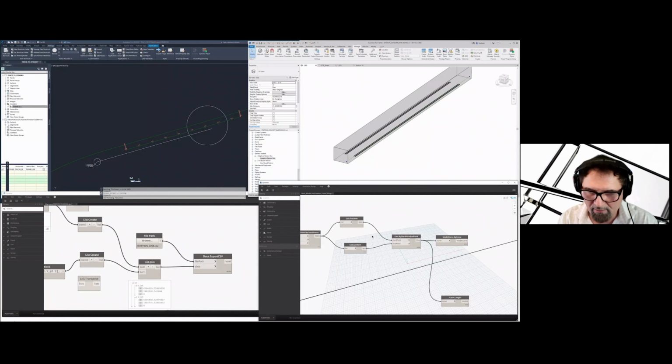Now, on a full-blown project, you would definitely not have that automatic. However, you would prepare your model. This requires special quality control so that all of your components are tied to some reference that is referenced further, so it propagates, and you can reduce the time it takes to update the Revit model from the modified civil alignment geometry in Civil 3D dramatically.